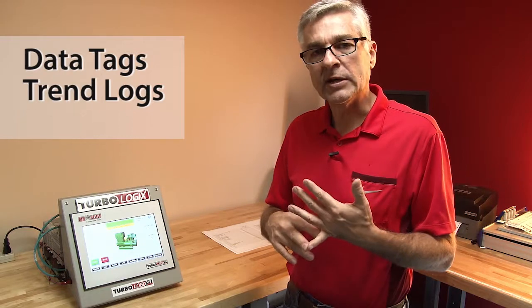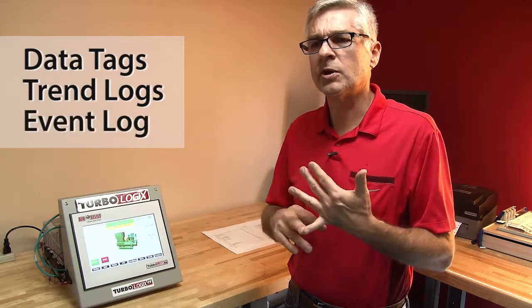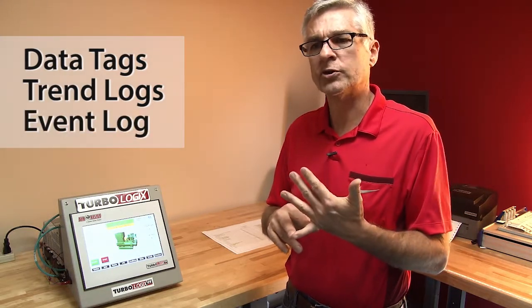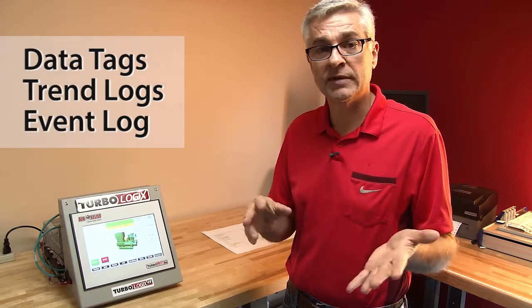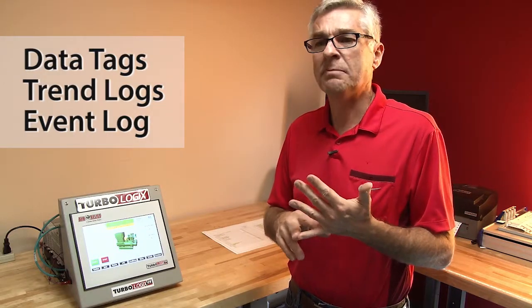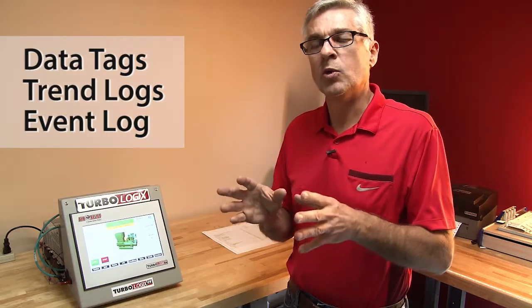And also on your event log. It's very important so that whenever you have an alarm or a trip on a machine, that is easy to identify and quickly identified. And by programming these labels in, we're able to make those changes, and whenever those inputs go awry, they'll show up on your event log with the correct name and the correct title on there.